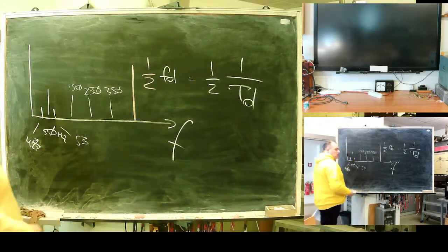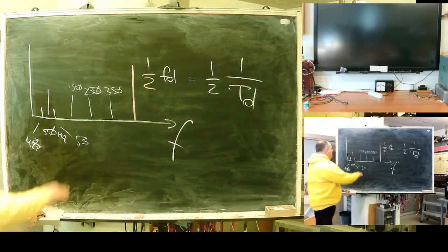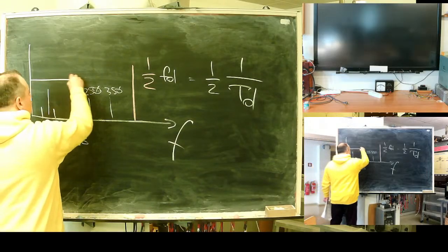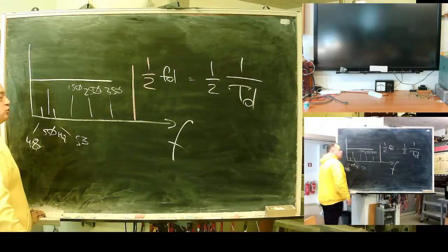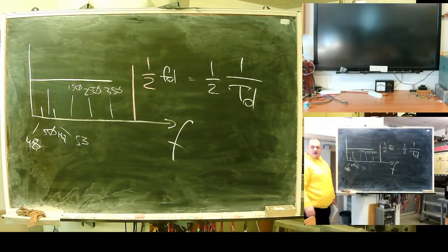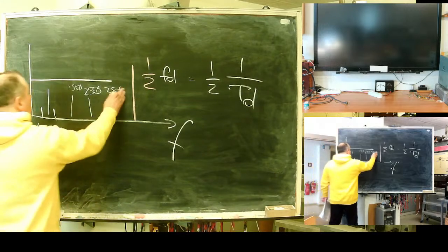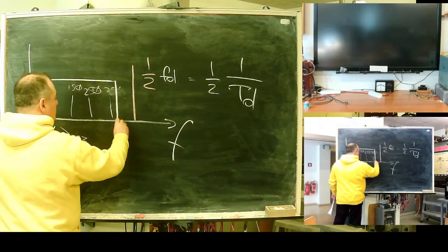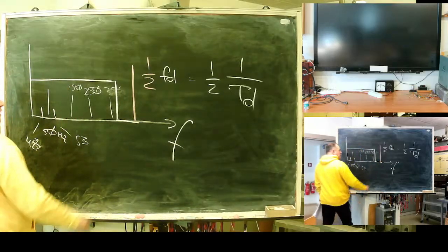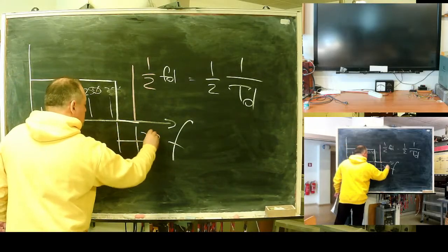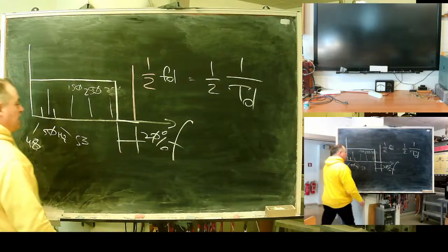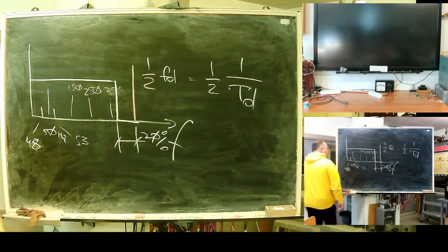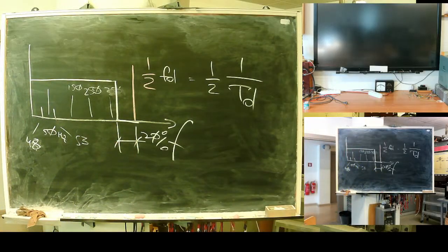And what's important? In this area, you may want to have a flat characteristic of your analog preprocessing part. And it should have at least a 20% safety gap before Nyquist frequency.